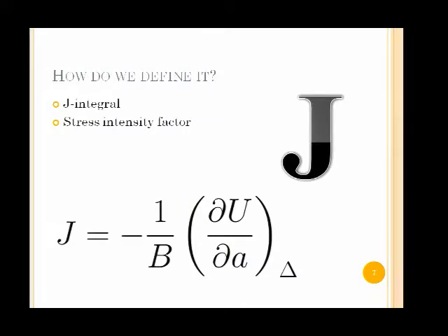So there's a couple ways to go about this. One way, which we're not going to talk about, but there's been lots of research into, is using something called the J integral. This essentially describes a sort of a fracture energy surface, and you're taking integrals and derivatives of everything. This technique is wonderful when you have multiple specimens with different notch lengths to test. So this gives you really consistent and accurate predictions, but you need a lot of specimens to test using this to get a very accurate value of J.